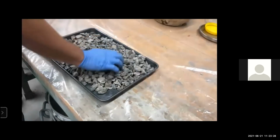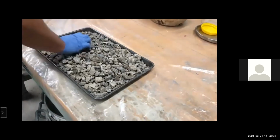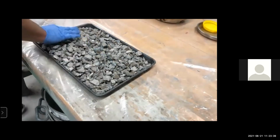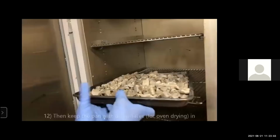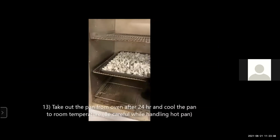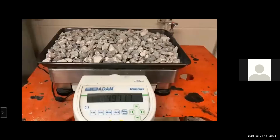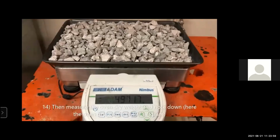Then we spread all the aggregates on this tray and allow this aggregate to dry for 10 to 15 minutes. So again we drain this aggregate for about 10 to 15 minutes. Then keep this aggregate in an oven for about 24 hours. Then take out the aggregate from the pan after 24 hours.